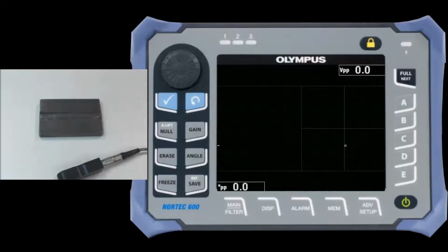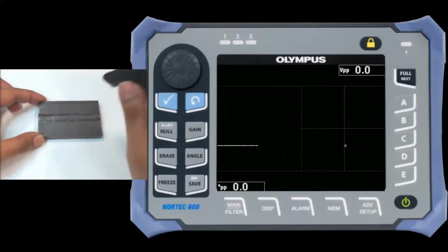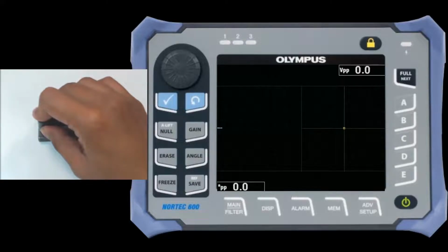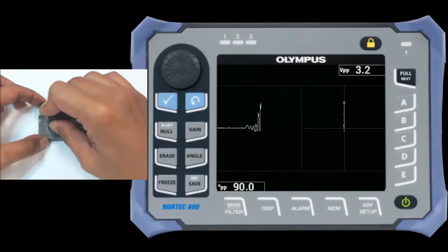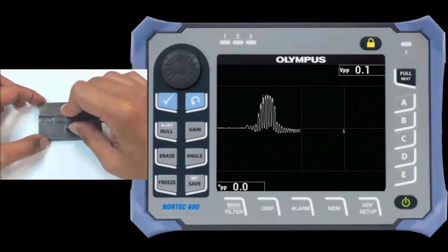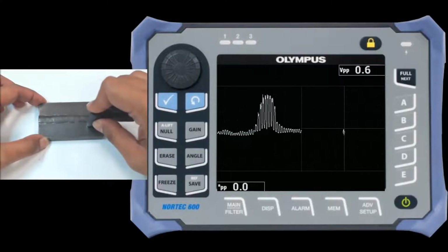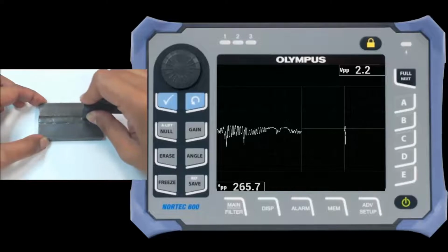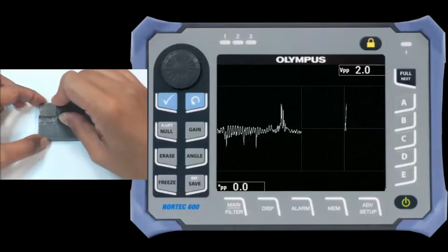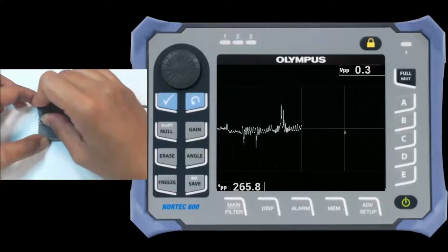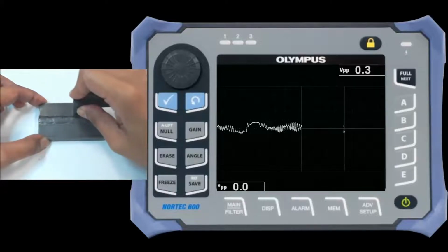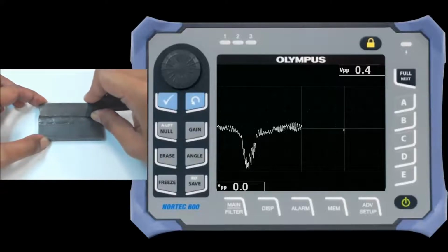And then we roughly scan the weld sample again. Okay, so first would be on the heat affected zone. We try to scan and see whether we can get the notch on the toe. So that's the one. Okay, so we just continue scanning roughly the weld sample. Next is scanning the weld face. As you can see, there's a little drift, but you can still see one of the actual defects. And now this is the longitudinal defect. After which you scan the other heat affected zone where there is an axial defect, which you can see on the display.